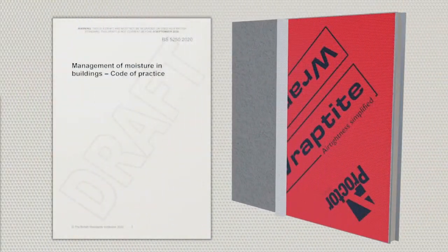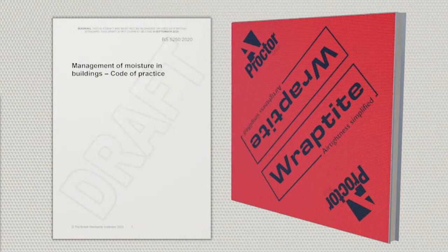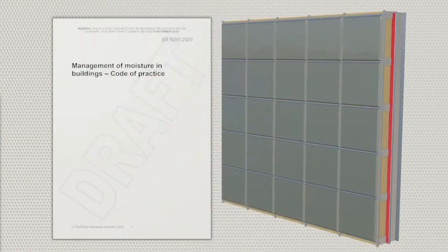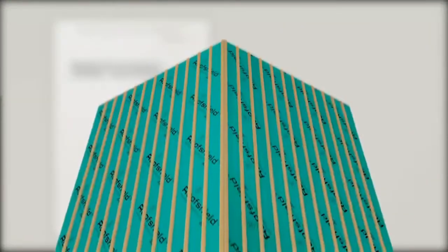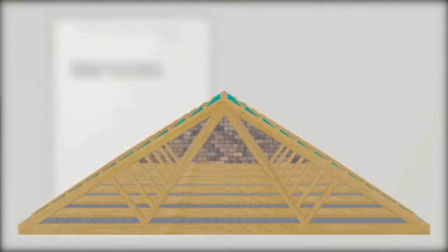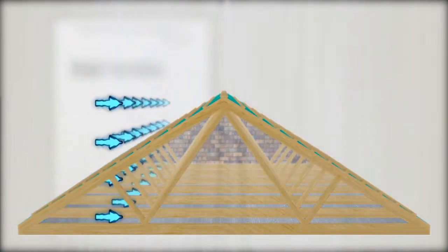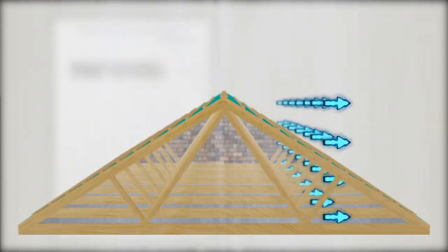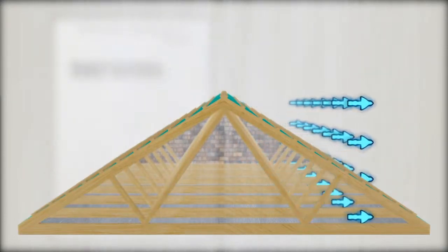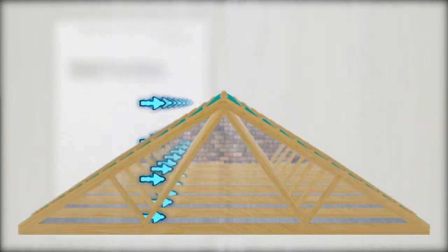In Appendix K covering wall constructions, vapor-permeable air barriers like our Wraptite membrane are incorporated, including their use with additional external layers of insulation. This recognises the benefits of utilising this type of membrane to simplify the reduction of air leakage rates. In roofs, Appendix L introduces a new construction type for non-ventilated roofs with air-permeable low-resistance underlays, APLR, under Section L5.4. While this type of construction was always allowed via third-party certification, this is the first time the benefits of air permeability in terms of condensation risk has been specifically addressed by the standard.